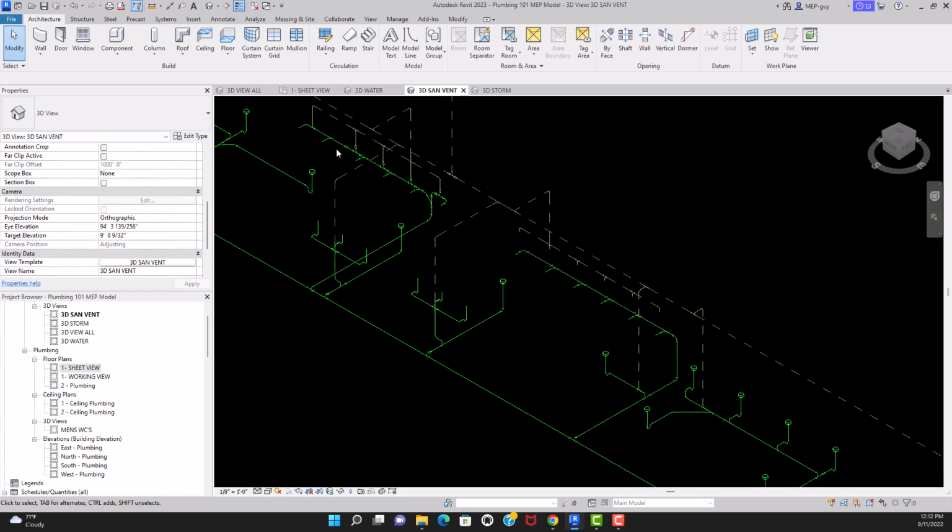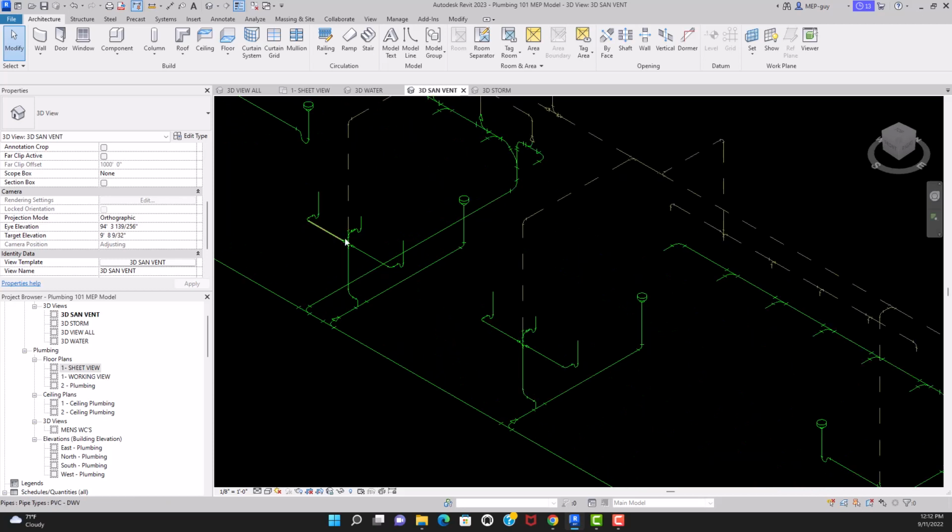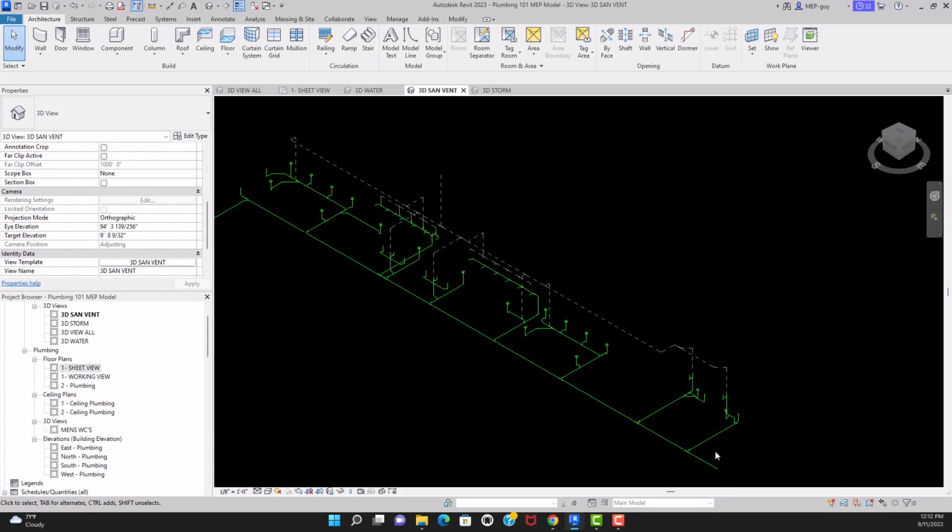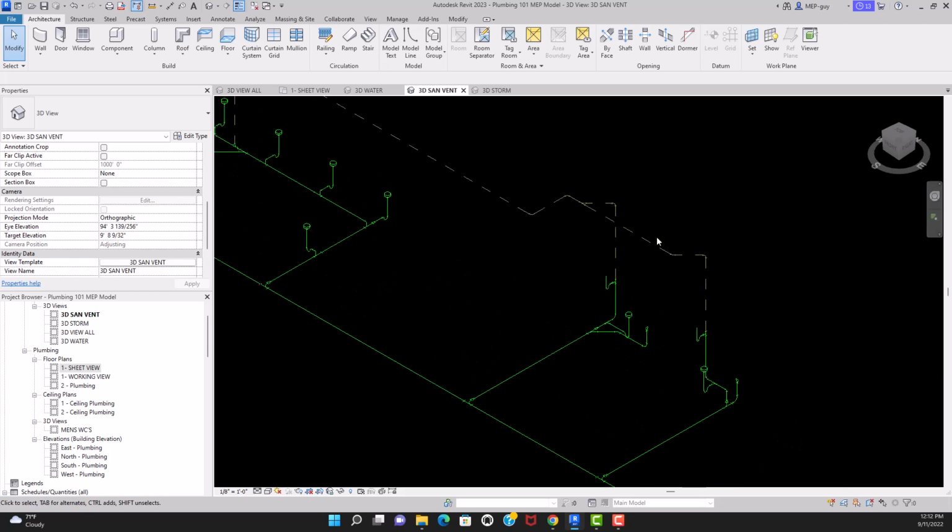And here we have some water closets. They are wall hung, so we'll talk about carriers, we'll talk about all the things you'll need to understand about how these things function. And then we have a combination vent right here for our lavatories. And then we also have down here some wet vents that I'll show you guys how to use, a wet vent for a bathroom group.